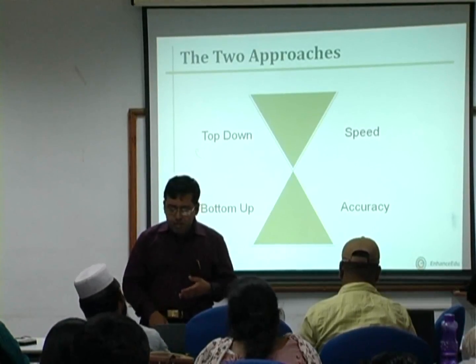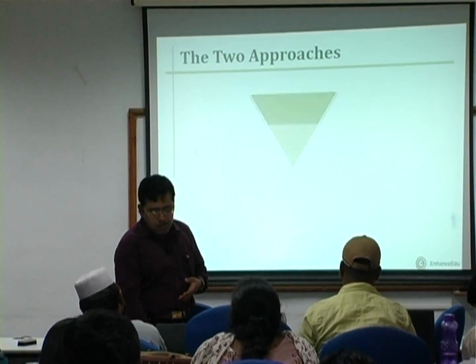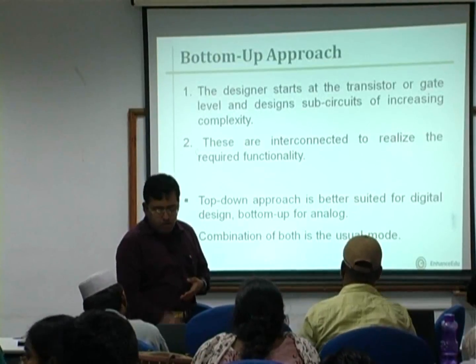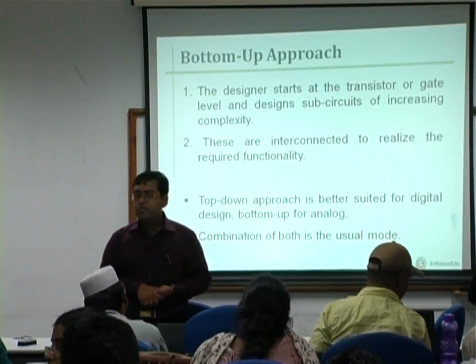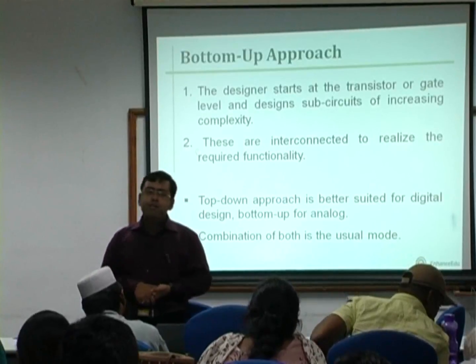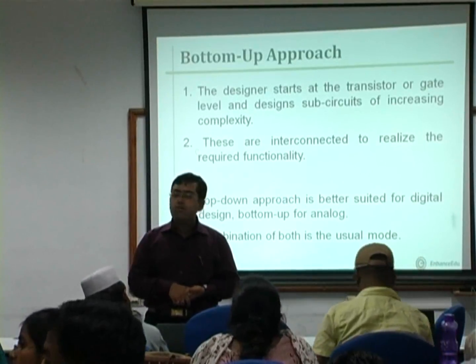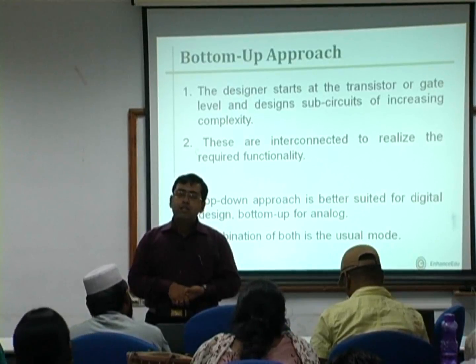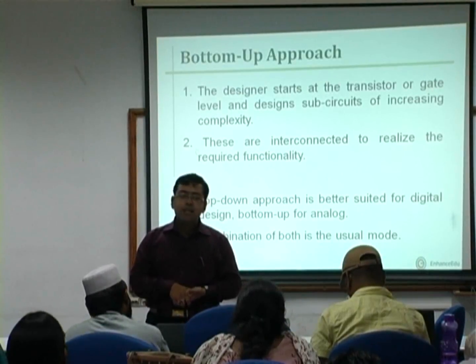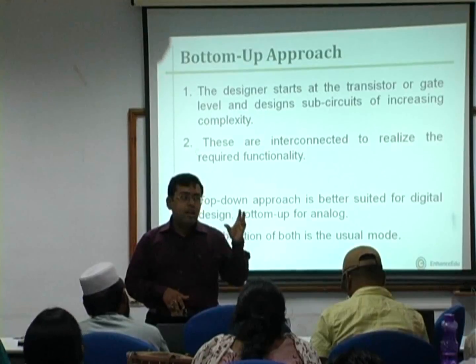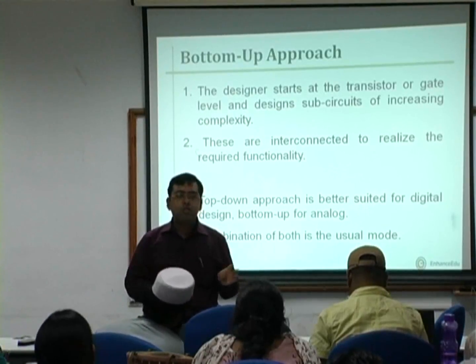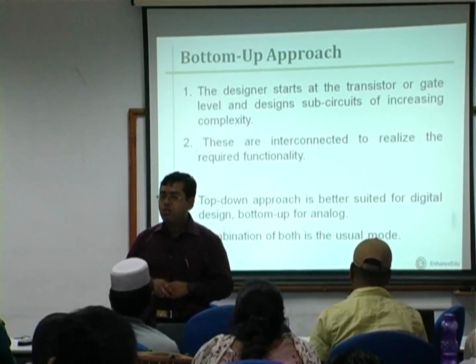So typically in digital design processes, we use the top down approach, where we are not so much bothered about noises and disturbances, because the digital circuits are designed in a manner so that a range of voltages correspond to logic 0 and a range of voltages correspond to logic 1.